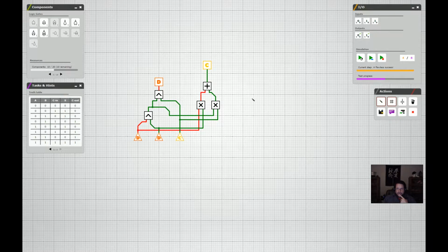Here we've got B and carry in being 1s and carry out is a 1, but not the sum. So we do make it through the XOR gate, but we don't make it through right here because Cn is also a 1. But we do make it through this AND gate and up into the carry. And that was apparently the expected output. When A is a 1, we expect sum to be a 1. Yeah, that worked.